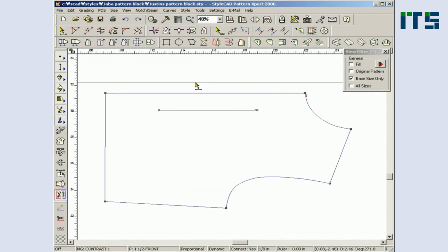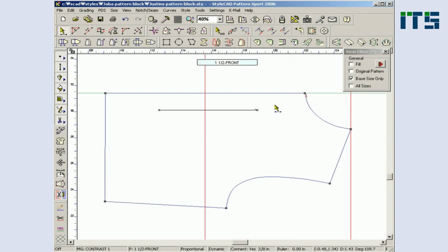Drag from the ruler area to make a guideline. Select a guideline with the Control and Tab keys down. Type a relative distance and click either side of the selected guideline to create a parallel guideline.